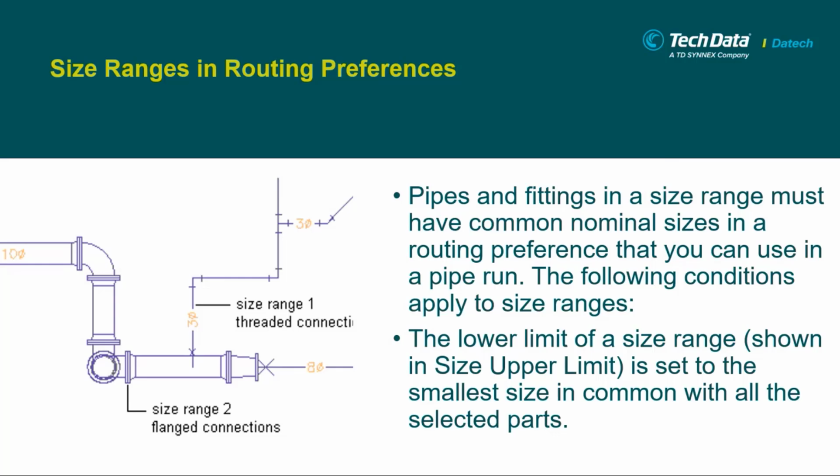There are various size ranges available, which are again part of your libraries. You'll find the fittings automatically selected based on the pipe sizes. If other equipment or instruments such as reducers or flanges are to be utilized, you can find the flange compositions, and the upper and lower limit sizes can be automatically selected, and you can proceed further.